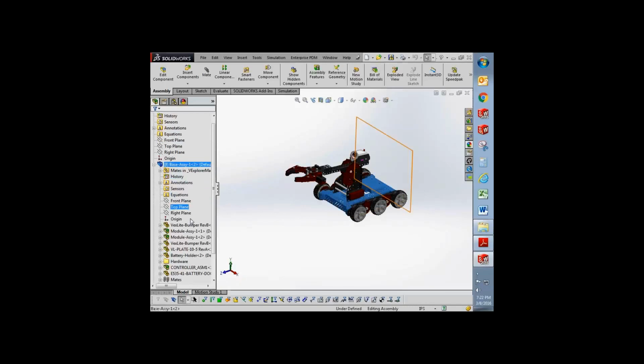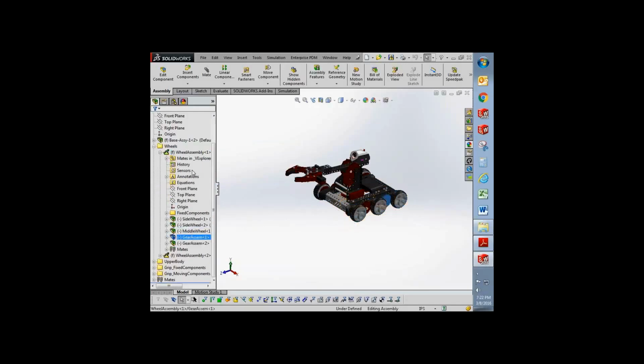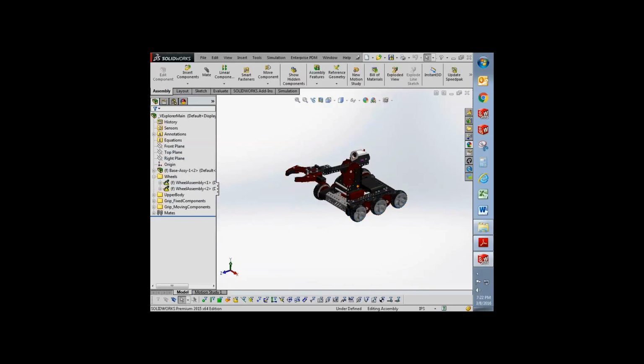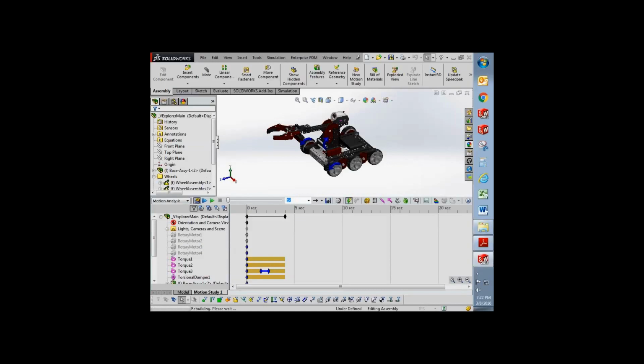And the other trick you can do is we do support flexible sub-assemblies, and within these flexible sub-assemblies we have all moving parts, but this main assembly is fixed. Then just fix all these parts. It just makes it more efficient. So in this example, I'm just worried about this part here. If I go to the motion study and solve it, you'll see that it takes a longer time to solve. I'll open the pre-optimized version, and I'll show you what is fixed there.